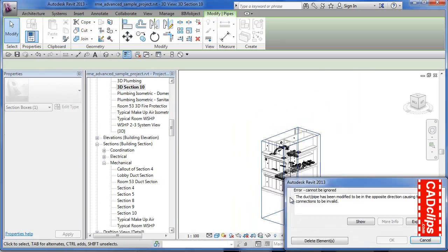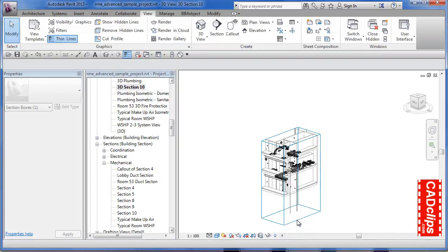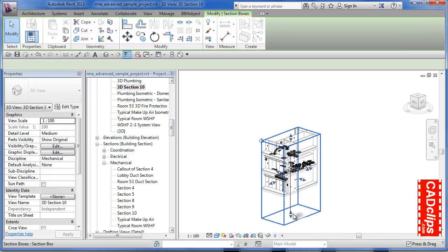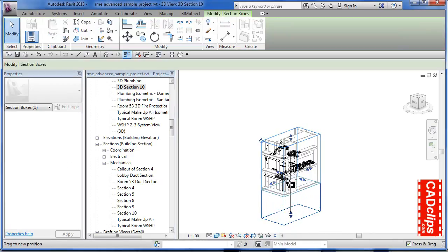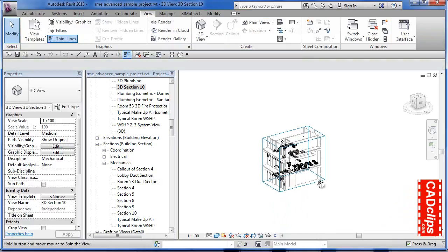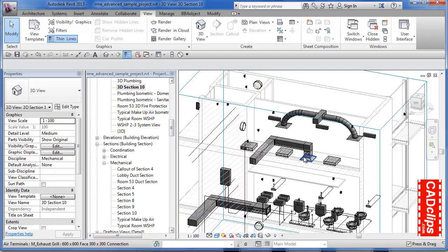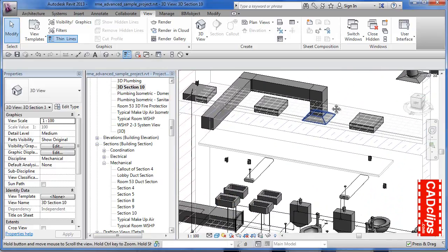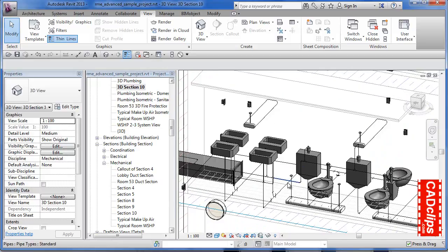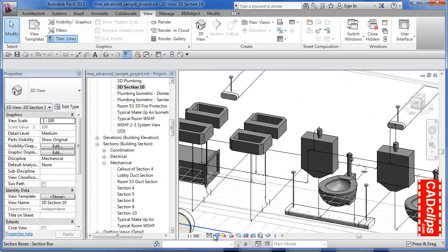and then you can pick on them and, oh, sorry about that. Pick on this section box and then grip it, pull it up, etc. I mean, you can take these and put them on views and stuff as well, but I think when you're beginning, it's nice to be able to pick an area that is of interest and then zoom in and have a little bit closer look at what's going on. Again, pay attention to your detail level and your scale.